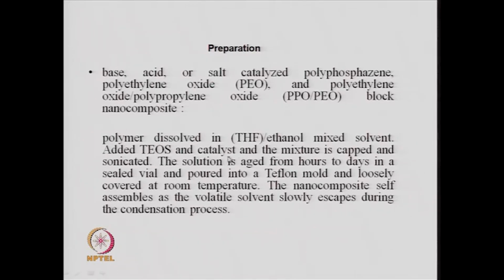the hydrolysis and condensation. Then the mixture is capped and sonicated, and the solution is aged from hours to days in a vial and poured into a Teflon mold, and it is loosely covered at room temperature. Since it is loosely covered, the solvent will slowly escape and the nanocomposite will form by self assembly. It will self assemble and the solvent will escape during the condensation.